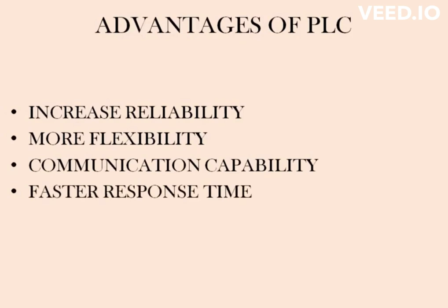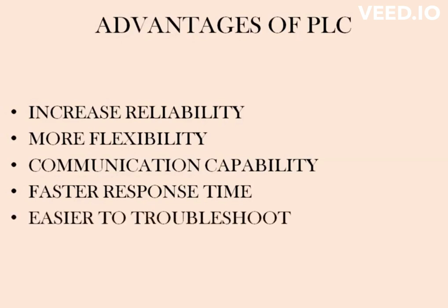The next one is faster response time. It operates in real time, which means an event taking place in the field results in the execution of the output. The next is easier to troubleshoot. It has LED indication to easily find the faulty I/O and fix the problems. The user can display the control program on the monitor and watch it in real time as it executes. By using all these, we find more advantages in the PLC.